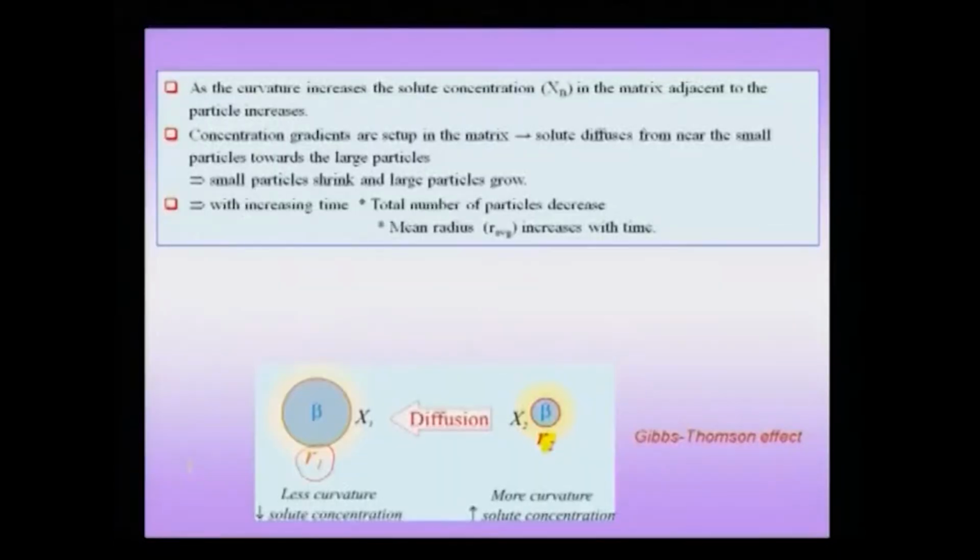If I understand this mechanism, I can hypothesize how, in an assembly of various sizes, smaller precipitates will tend to vanish and larger precipitates will tend to increase in size, therefore reducing my interface area and the energy of the system. Now, the composition of the solute which is in equilibrium with the precipitate is not an independent number, but a function of the curvature.